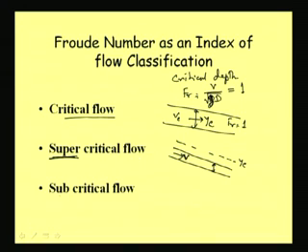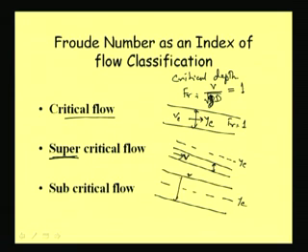And then when we talk about subcritical flow, this depth will be more than the critical depth, suppose it is critical depth yc. So, then it is called a subcritical flow. Okay. And here again the flow velocity is less than the critical velocity. If I write this as V1 and this as V2, then V1 is greater than Vc here, and V2 is less than Vc.